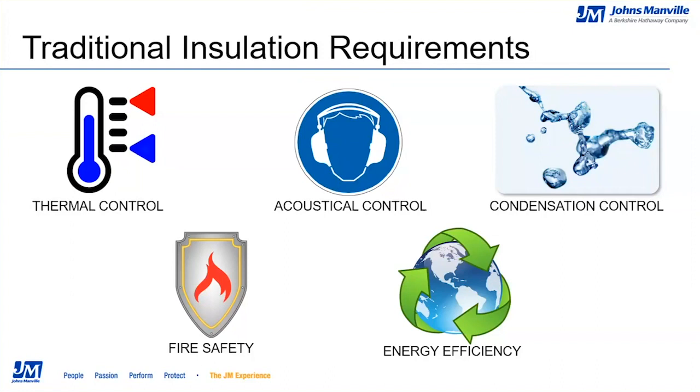For fire safety, the flame resistance of materials is a primary consideration. Some materials are non-combustible, and some have fire-resistant chemical additives to provide flame resistance. In HVAC and mechanical systems, all materials are required to meet a fire hazard classification rating of 25 flame spread and 50 smoke developed to protect building occupants in the event of a fire. Finally, insulation saves energy, and in many cases, insulation uses recycled materials. This gives insulation products high marks for environmental friendliness.